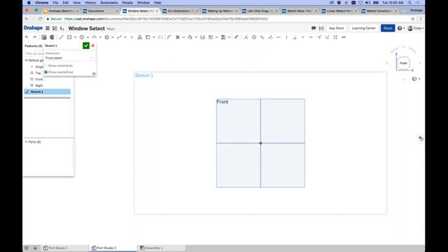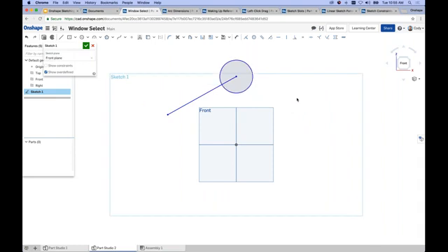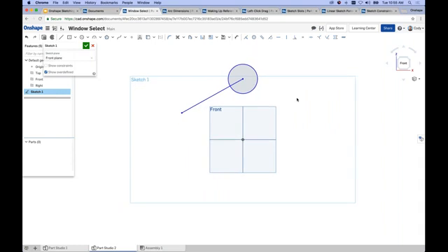Now another one, these are the kind of the obvious ones, but I do want to point them out. L for line, right? C for circle. Those are kind of the easy ones. Again, these are just some of my personal favorites. Another is coincident. I is the keyboard shortcut for coincident.